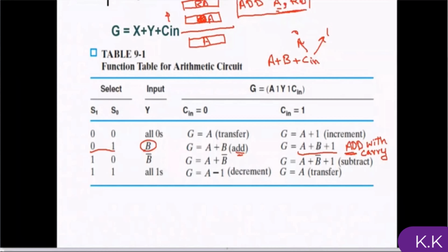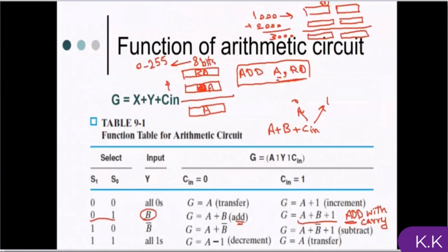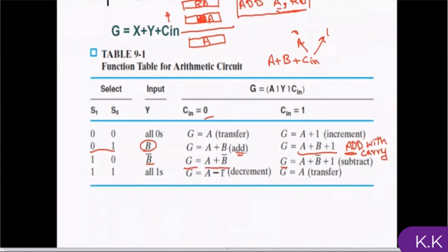That is necessary for performing operations larger than the capability of the processor. In any processor, the maximum size of data that you can process is n bits, but if you want more than n bits, you should divide it into some smaller parts, perform them one by one and combine the results. Adding two 16-bit numbers with an 8-bit processor is done this way. First, for the low bytes, find the summation by using a simple add. For the next 2 bytes you should use add with carry. The carry of the previous addition should be considered.